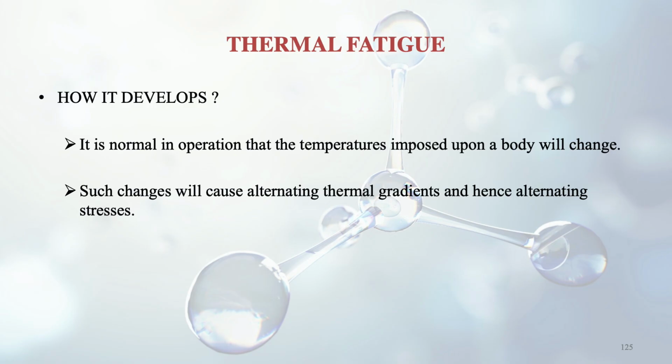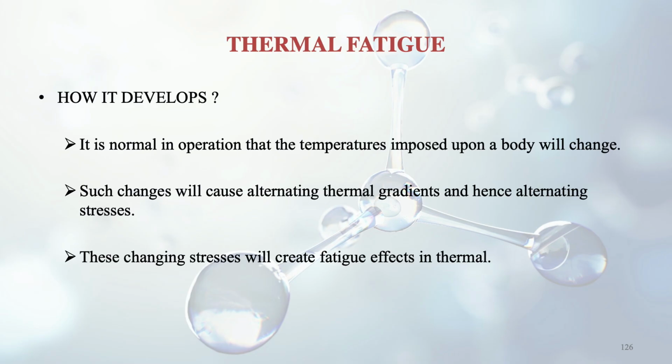So such changes can be there, and this will cause alternating thermal gradients and hence alternating stresses, like we discussed earlier for mechanical fatigue also. So this is thermal fatigue. These changing stresses will create fatigue effects, and this phenomenon is known as thermal fatigue.